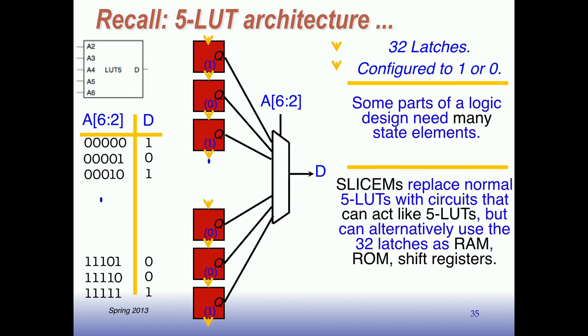Okay, and then the final thing I was talking about, I said that FPGAs have lots of ALUs in them. And these are ALUs that do add and multiply and logical operations. Now, logical operations are pretty efficient in LUTs, and addition can be made fairly efficient using the LUTs with the carry chains that I talked about. But multiplication, turns out, is a pretty expensive thing to implement using LUTs. And multiplication comes up in a lot of the computation that we do. So